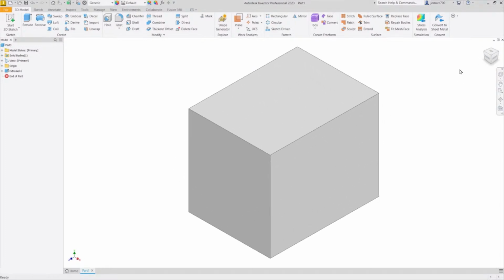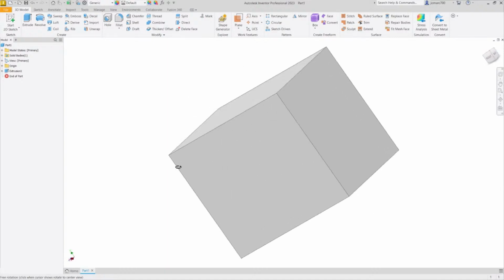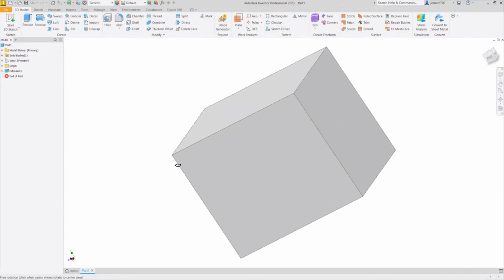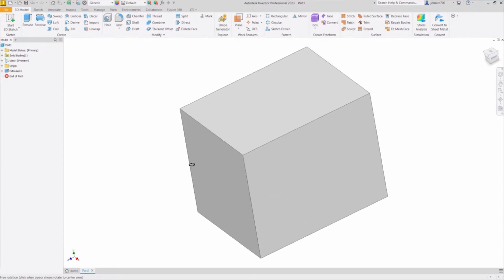And lastly, sharing to you the last option to rotate our 3D model is simply hitting F4. Notice as I hit F4, we have this circle and these lines. As I hover over this line, notice the change of my cursor, and as I left click and move my mouse, I am rotating this object with respect to a vertical axis.